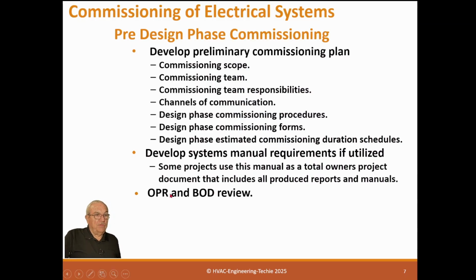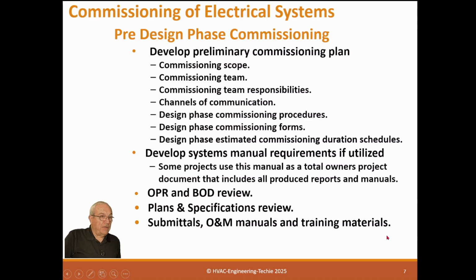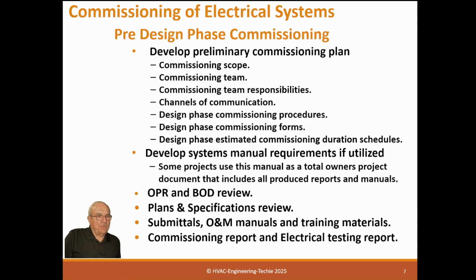OPR, the BOD review. Now, the BOD is the basis of design, and that is to be done by the engineer. It's basically a narrative of his design, and the narrative explains how his design meets the OPR. The plans and specifications review, submittals, O&M manuals, and training materials. Commissioning report and electrical testing reports. These are all part of the commissioning plan. You're explaining exactly what you're going to do and what these materials are going to contain.